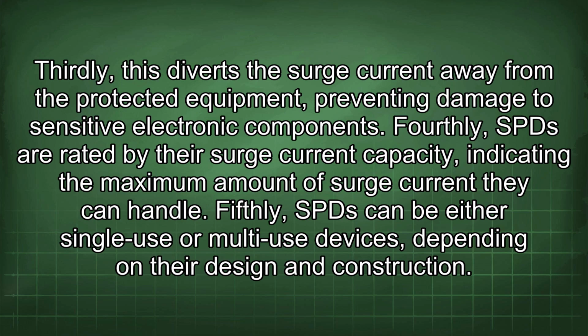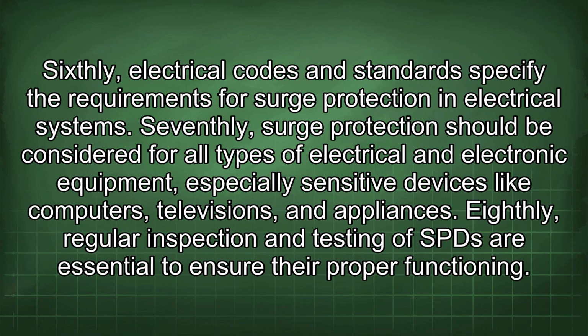Fifthly, SPDs can be either single-use or multi-use devices, depending on their design and construction. Sixthly, electrical codes and standards specify the requirements for surge protection in electrical systems. Seventhly, surge protection should be considered for all types of electrical and electronic equipment, especially sensitive devices like computers, televisions, and appliances. Eighthly, regular inspection and testing of SPDs are essential to ensure their proper functioning.